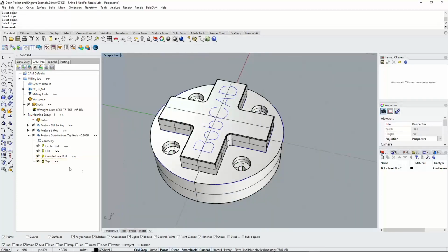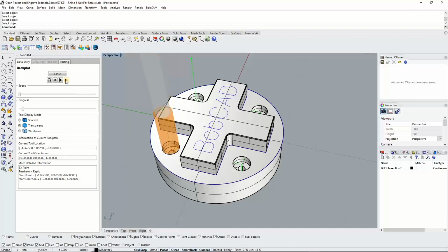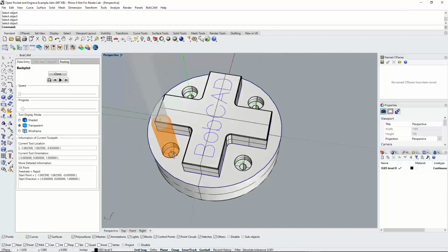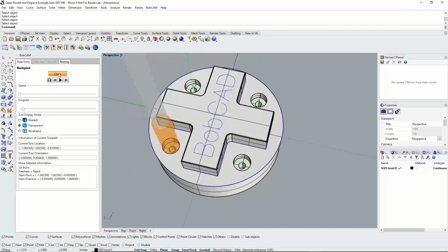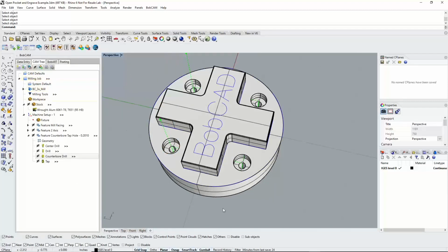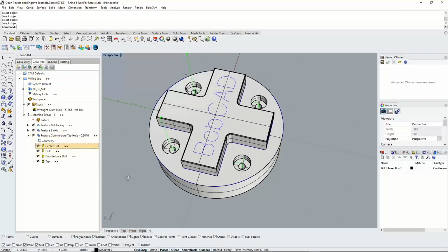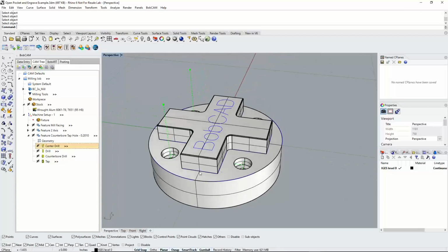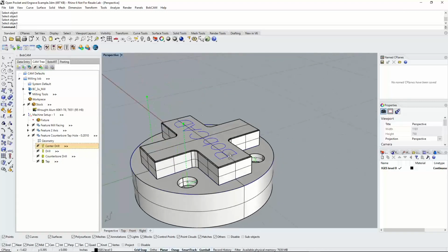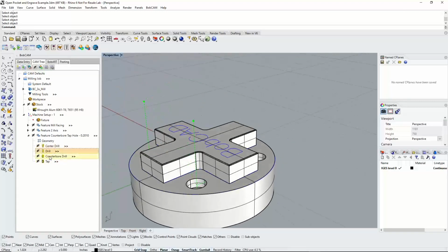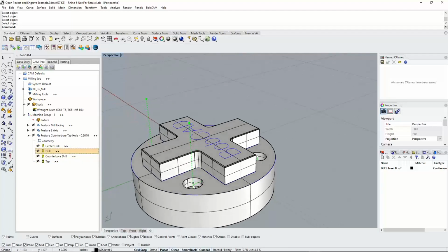inch deep, compute. And so now if we watch it and we back plot this guy, that should be what we're looking for right there. So it's just going to that 1/4 inch deep and then leaving. So that looks a lot better. Now, the other thing we'll notice when we look at all these tool paths is where it's linking. Right now, and you can see it in all of this, it's linking through the part.